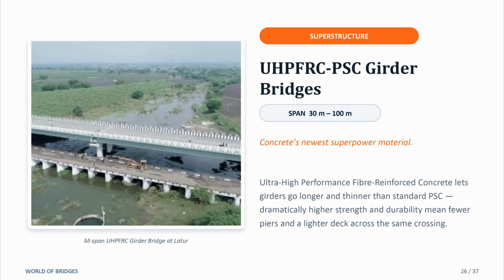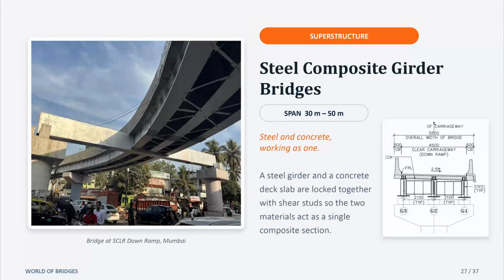This is the 60-meter span UHPFRC girder bridge at the Latur. Steel composite girder bridges: swap concrete girders for steel ones and connect them to the concrete deck slab with shear studs, and the two materials act as one composite section. Steel handling tension, concrete handling compression. Same 30 to 50 meter span but a different material story.